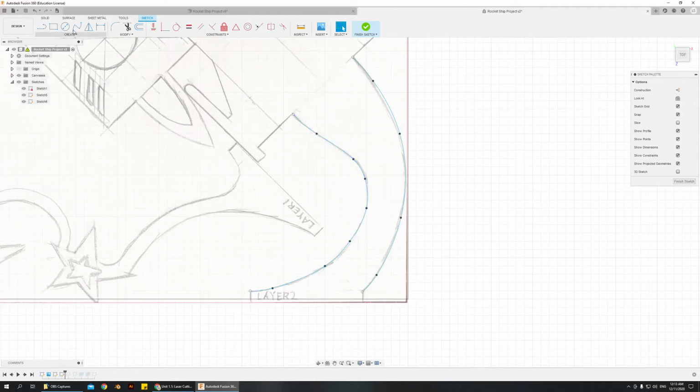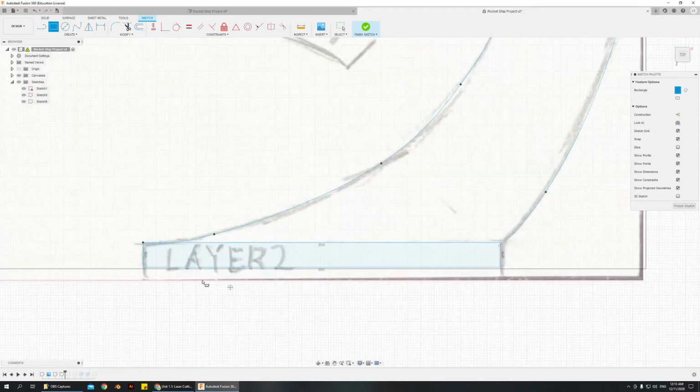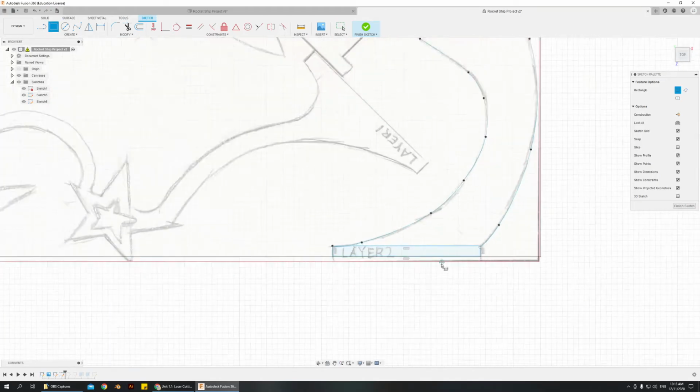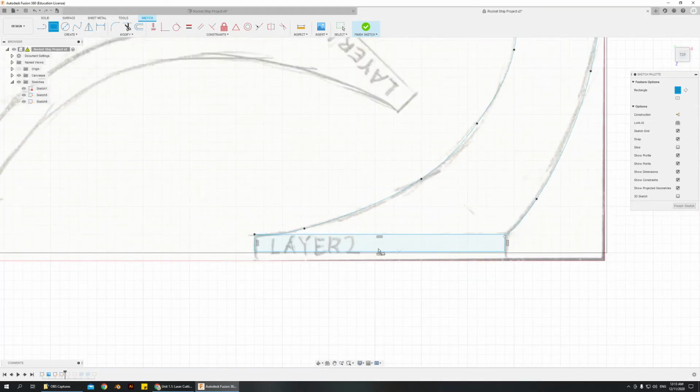And then I just took a rectangle and made it from this point to here. Now you have to be careful, like if you look at the bounds, that's the max, so I have to make sure that I'm not going beyond that. I dimension the rectangle, 0.25, or no, 1/8, and then that's actually too far, right?